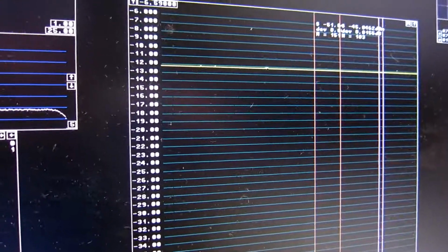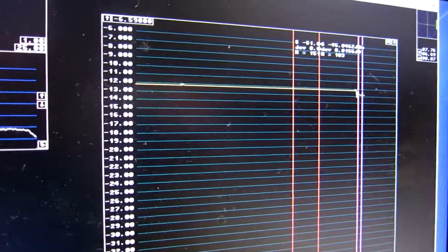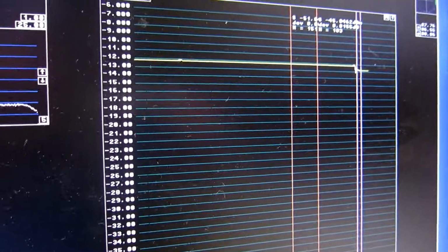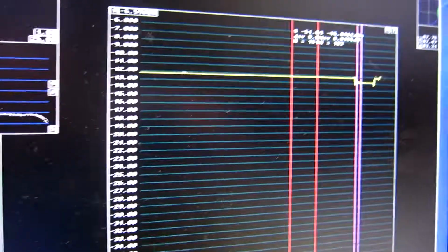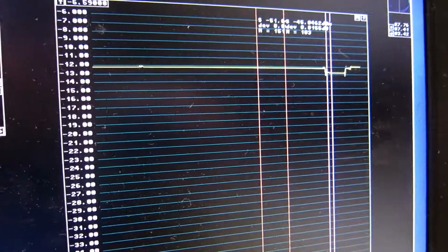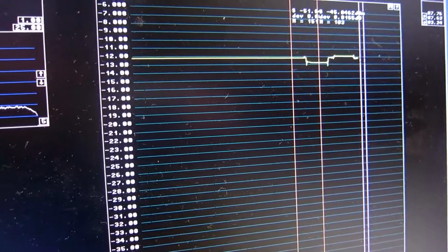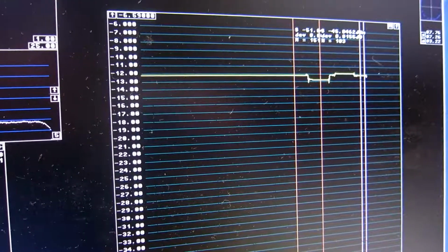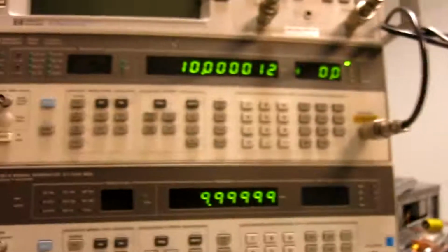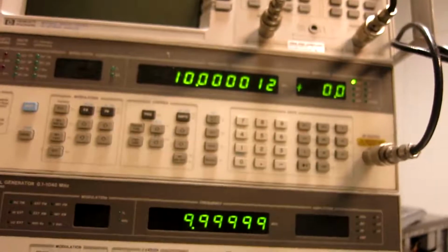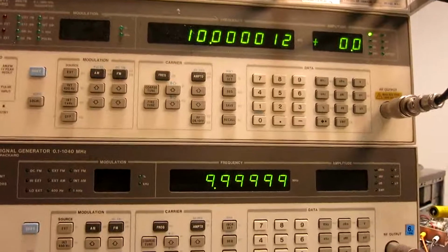Now I go down. That was clearly not good. Up, back, and up one more. Yes, that was better. And one more. Not so good. So, at this power level, the offset I need is 12. That is 1 Hz higher in frequency.